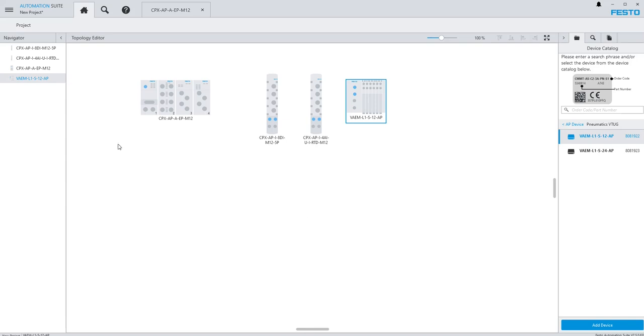So you'll notice in the AP-A portion, we have a 1, a 2, a 3, and a 4. What this is doing is counting up the modules. In the CPX-AP-A manifold itself, we can have up to 15 devices. This is up from the 10 that we could have on CPX standard. So it does allow you to have more devices on there.